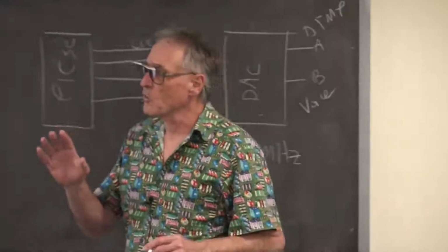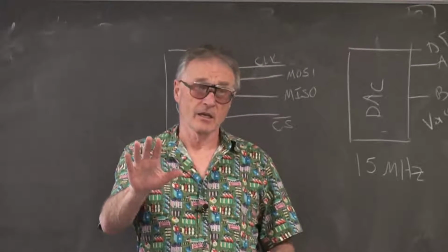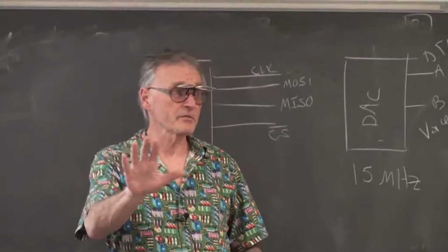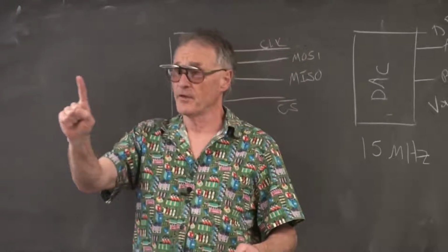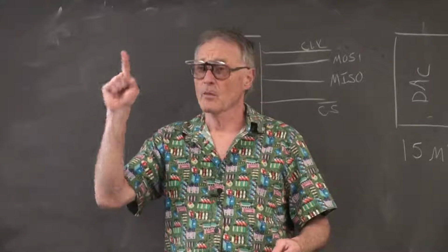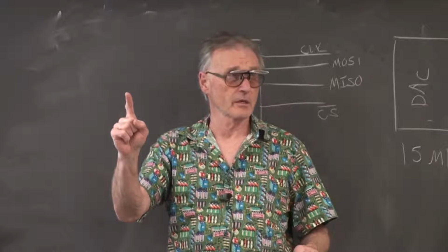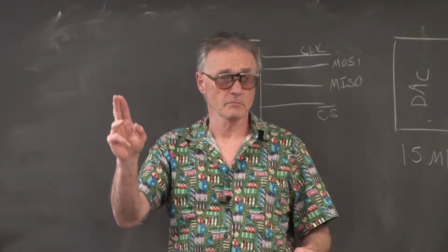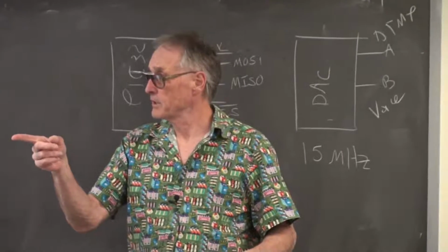But I think you're going to want, for simplicity, for sanity's sake, to minimize the interrupt service routine complexity. Write one interrupt service routine, which is running at a fixed rate, which you get to choose, and put all of the synthesis in that interrupt service routine. Any more detail?